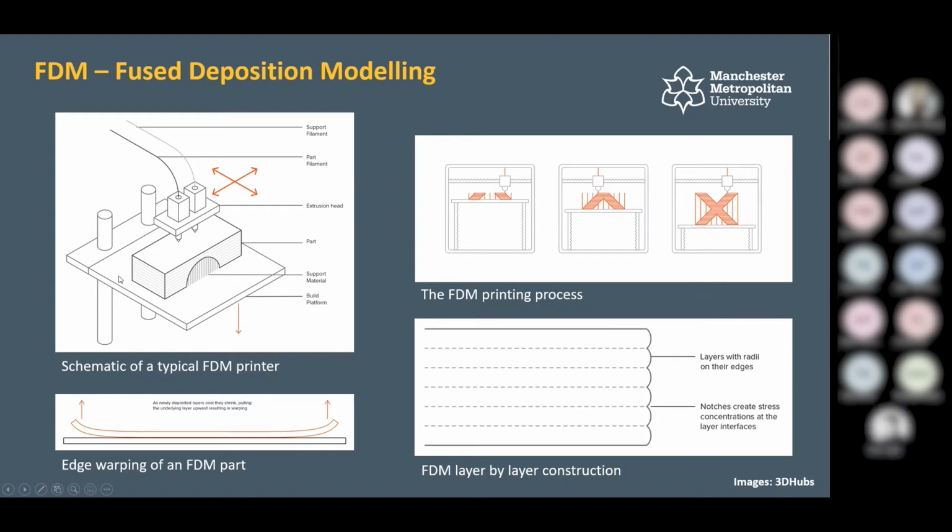Another thing to consider as well is to try not to use the maximum amount of a build plate. For instance, this model here might be fitting within the build dimensions, but because it's one flat surface area spread across the whole thing, you might start getting warping edges. When the material is hot to begin with, as it cools down, it can't keep up with the heat of the plastic above it. So it's going to start warping edges and you end up with a lot of failed prints.